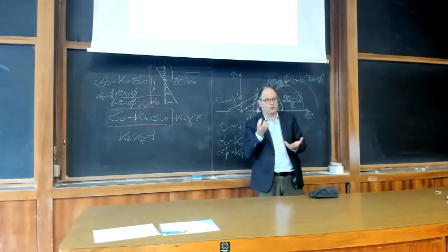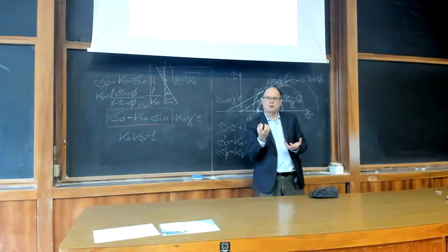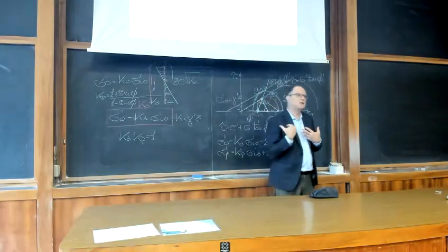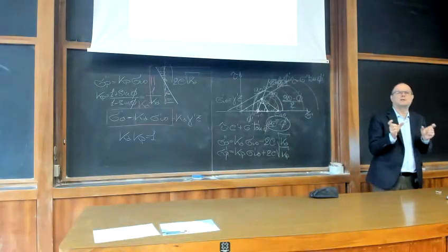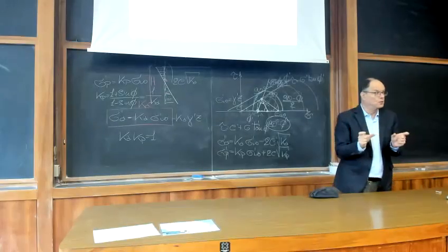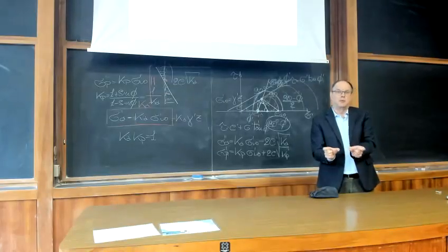It depends on the soil beneath your foundation. So we should talk in terms of bearing capacity of the soil and of your foundation, because as you will see, the bearing capacity, the limit applied load, depends on the two things, both the foundation and the soil beneath it.